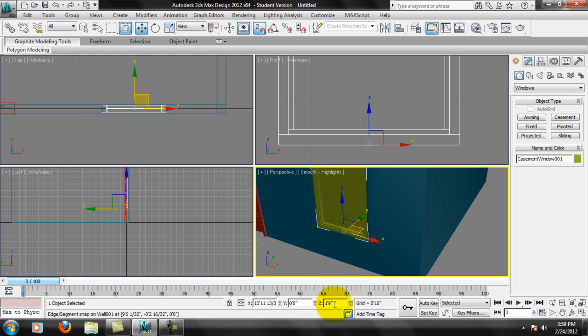So what if we knew that we are, let's see, 21 inches from the base, right? So we're 21 inches. What if we didn't know what point we wanted to move it to, but we wanted to enter more like relative coordinates? This little guy here, if I select that, now you'll see this changes to offset mode. So now I can just enter how far I want it to offset. So I'm no longer in the Cartesian coordinate system anymore. So now I would have to enter how far I want to offset it, and that's exactly how far it will offset. Okay, so that's different than having your coordinate system here.